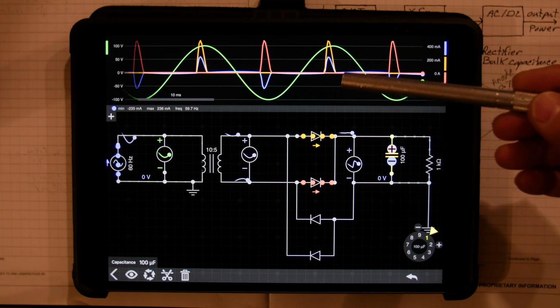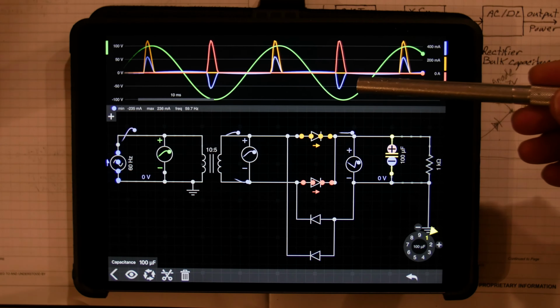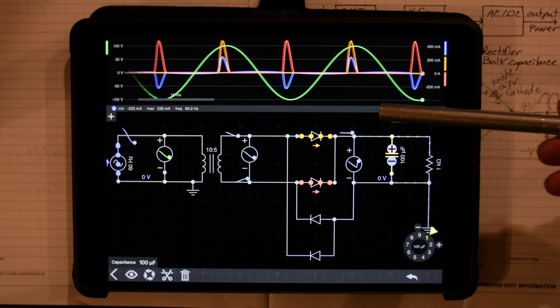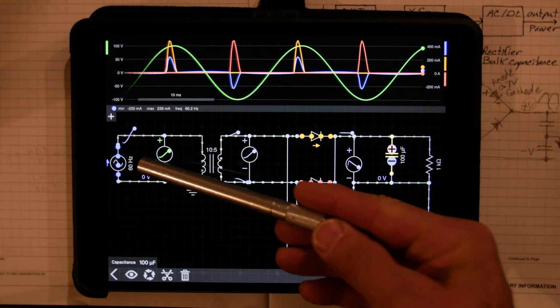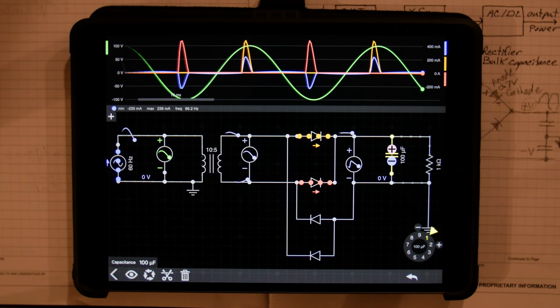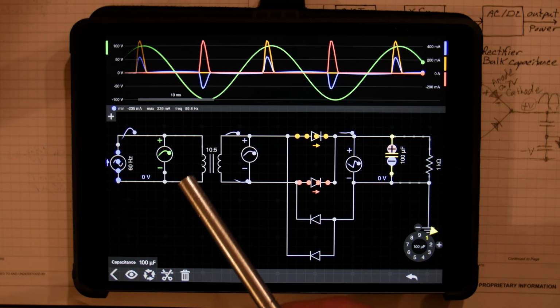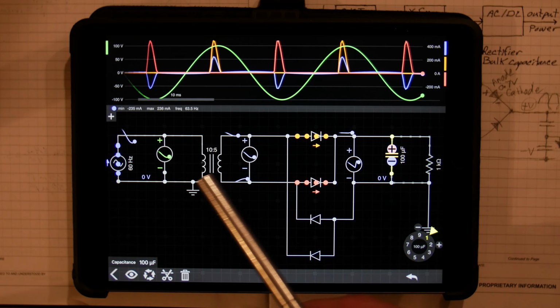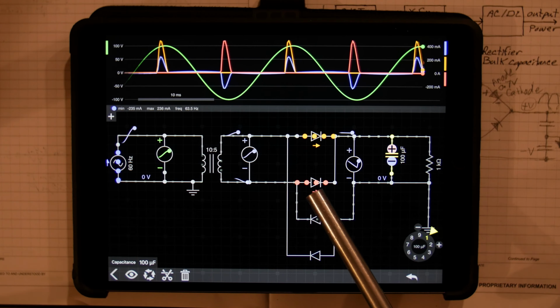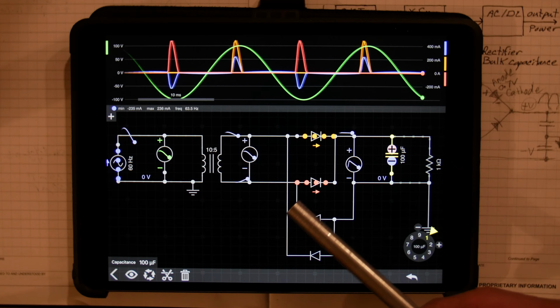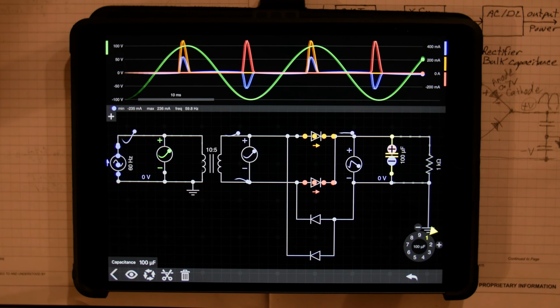But you can see by these large capacitors creating these high peak pulse currents that it's done so on the input as well. And that can be an EMI problem. So it would be beneficial for us to add a little filtering to help smooth that out a little bit.